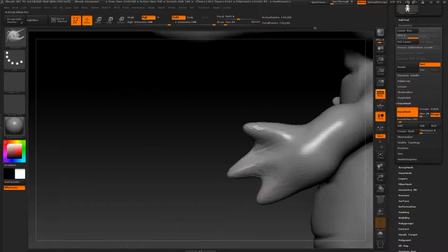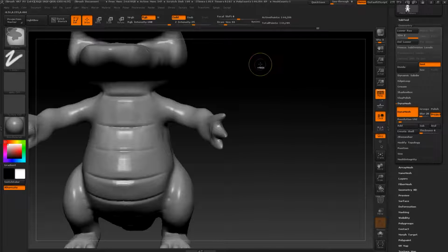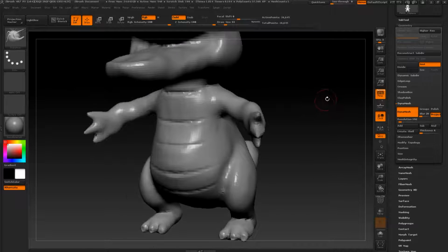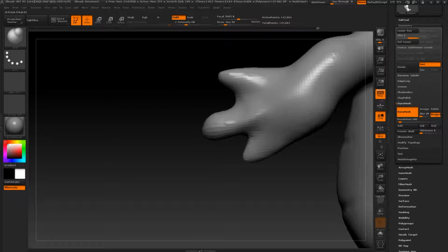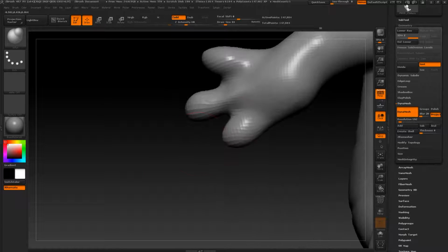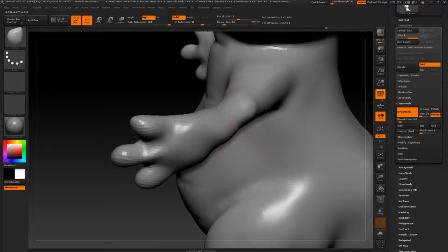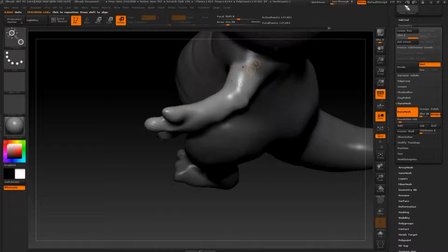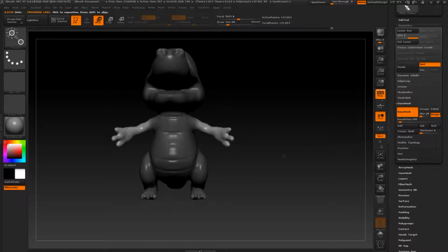Let's press Dynamesh again by pressing Ctrl and dragging a mask in the space. We have too little, but we can add another divide. B, inflate. This should be our elbow. Something like this. I think the arms are still too big, so let's shorten them up.